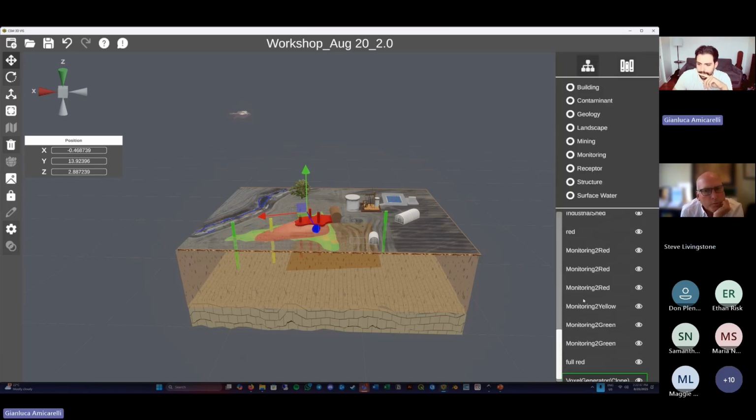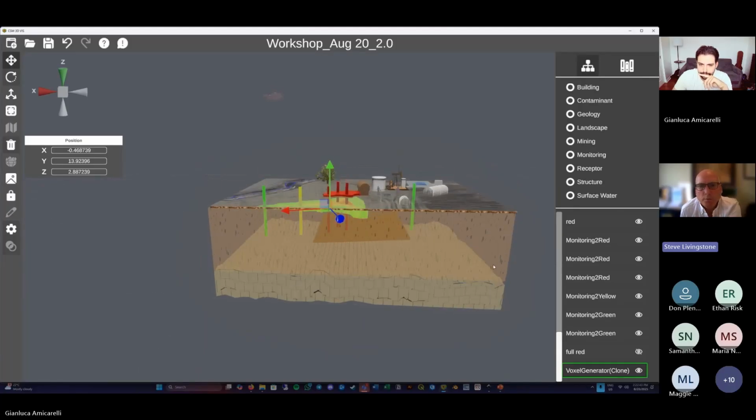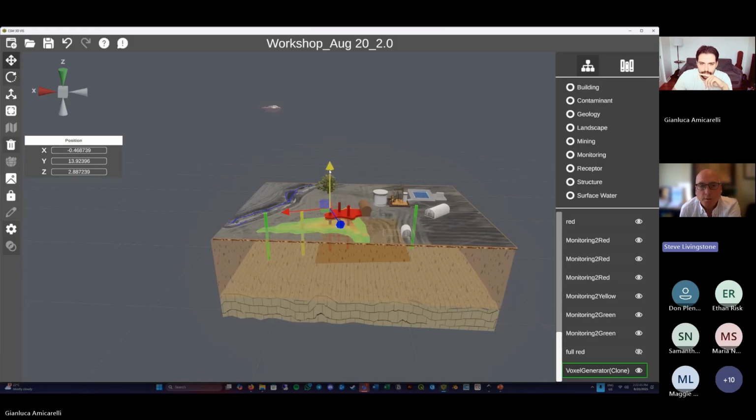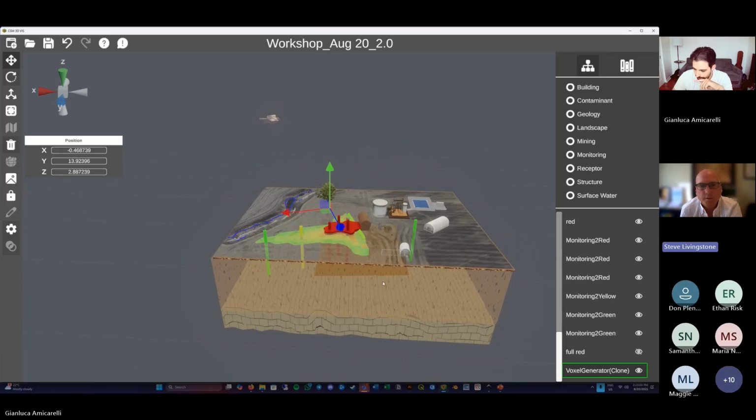Yeah, no, I was just going to say, John, look, this is from a 3D analytical solution, and it's really easy. It's an XYZ set with Z as depth, and we're able to bring that right in. This is a regular grid model, and so it's going from that first thing where you don't have any data, you just have some monitoring wells. You're trying to show basically the general morphology of your plume, and this one is getting into more advanced, where you're actually looking at an analytical solution for your plume too, which gives obviously a higher degree of interpolation, right?